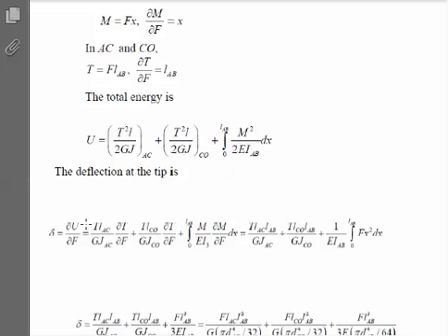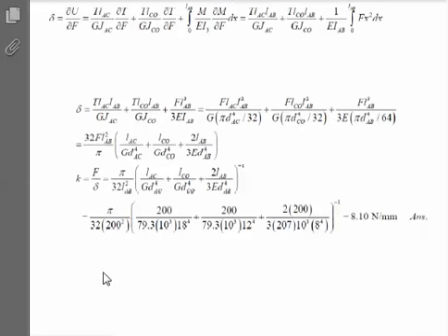Here is the partial of the energy term in the small diameter section. Here's the large diameter section of torsion. And here is the bending piece. And this one is now written as M times the partial of M over EI, where moment, remember, was F times X and the partial was X. So now we've got to plug all this stuff in, and eventually we will plug in what T is in terms of F.